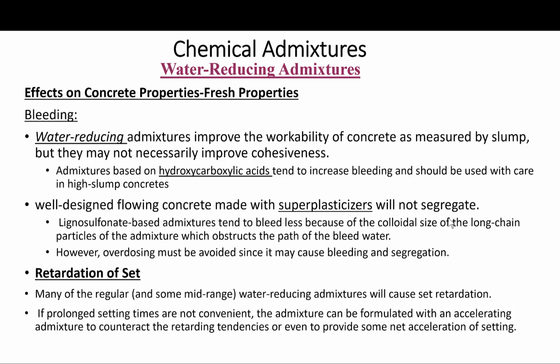Although well-designed flowing concrete made with superplasticizers will not segregate, overdosing must be avoided since it will cause excessive bleeding and segregation. And I've seen that, trust me. I have seen these problems in the field, and everybody scrambled to explain why, when, how, where, and all of that.